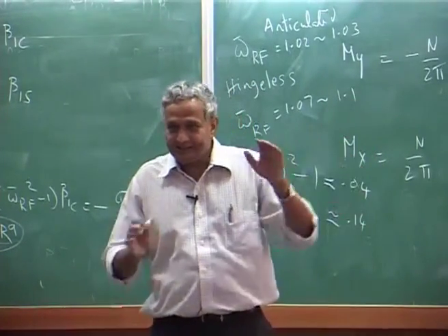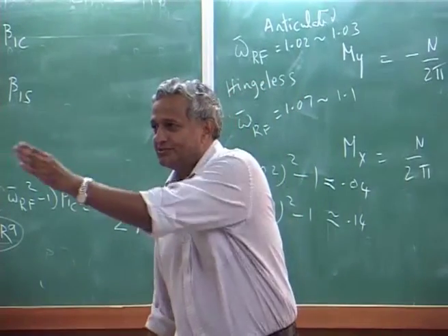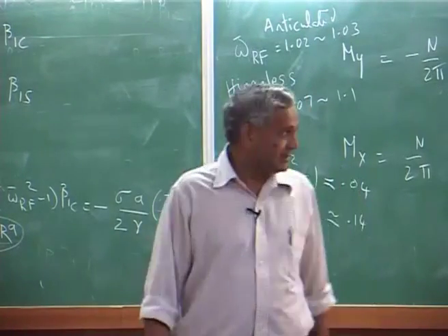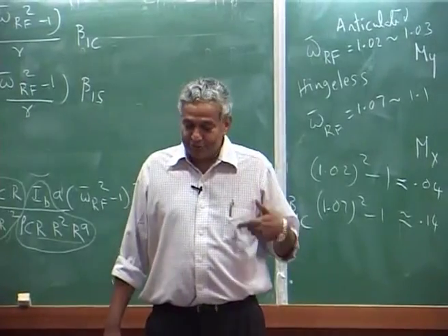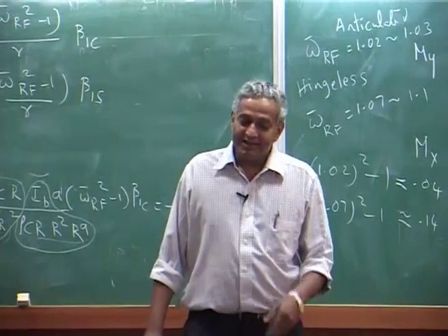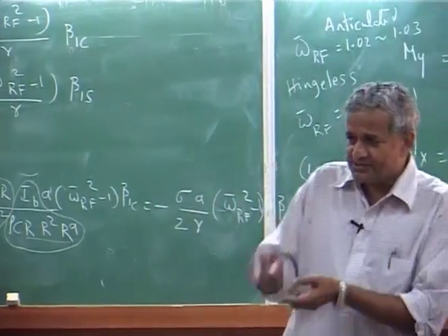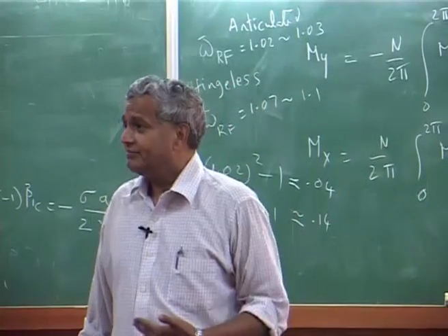Then the criticality of each feature gets changed or reduced just for the blade alone. So, in the design, you will be surprised, they may do the blade frequency calculation almost every day. If you are an engineer, you keep doing it, change some small stiffness, go rerun the whole program and then get the flap frequency.